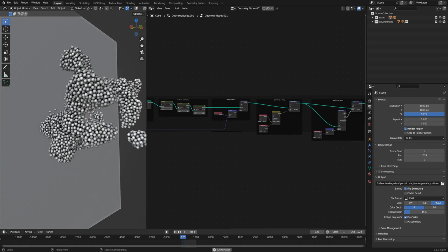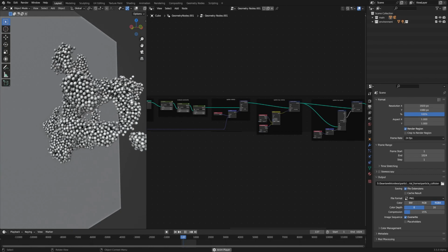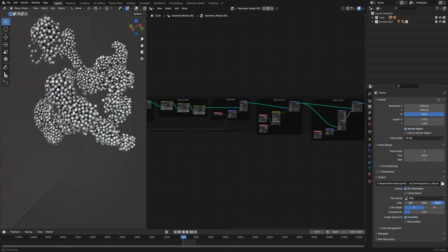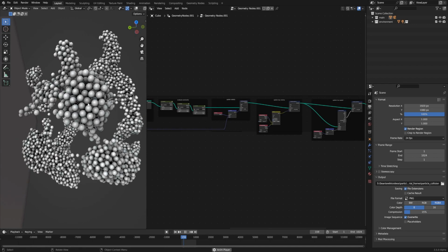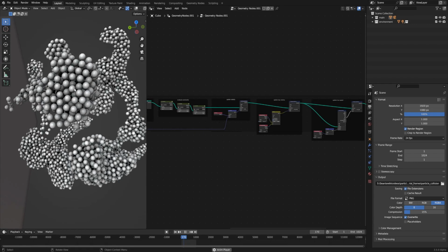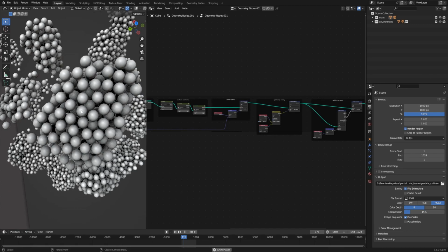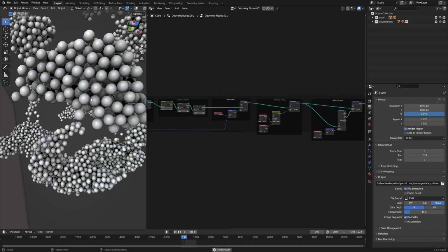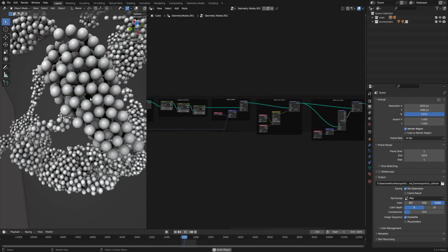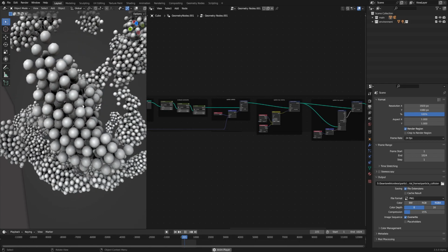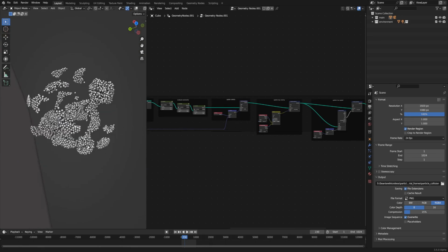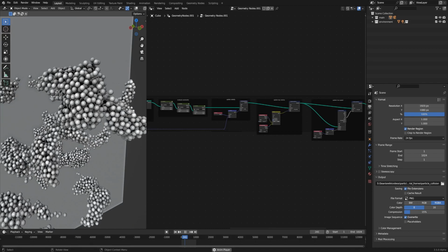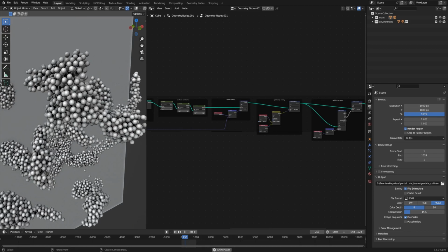And if we keep the simulation playing, we might be able to see some instances in which the particles bunch up at the edge of the sphere boundary. And if there's a lot of them, you'll actually end up seeing the collision constraints not work out. But because of the number of iterations that we're doing and the number of particles that we're working with here, the entire simulation seems to work quite well.